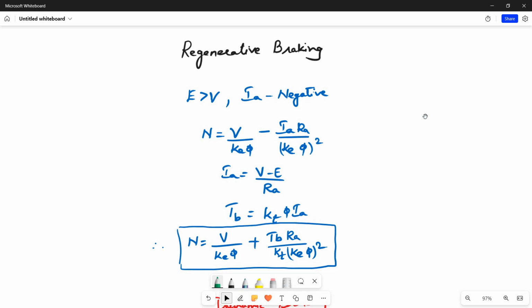Welcome back. This video is about braking of DC motors. The main theme of braking is to stop the motion or to oppose the motion. In braking, the motor works as a generator developing a negative torque which opposes the motion.